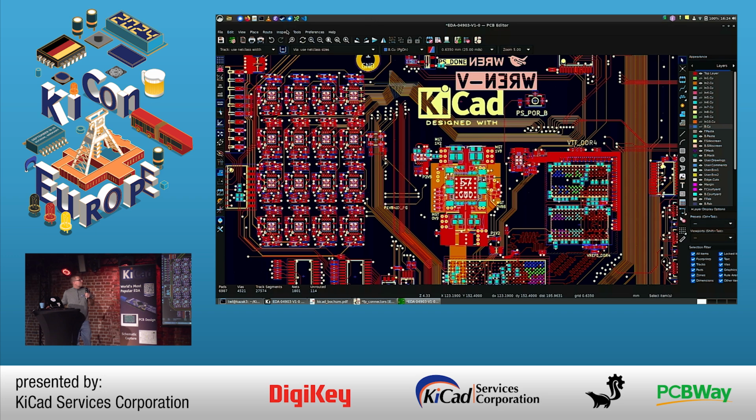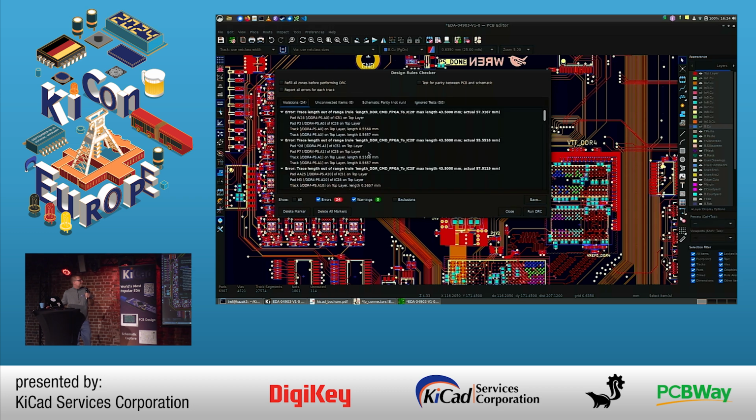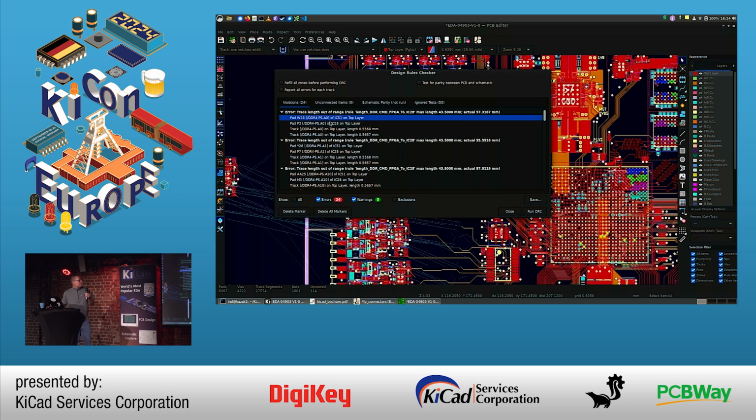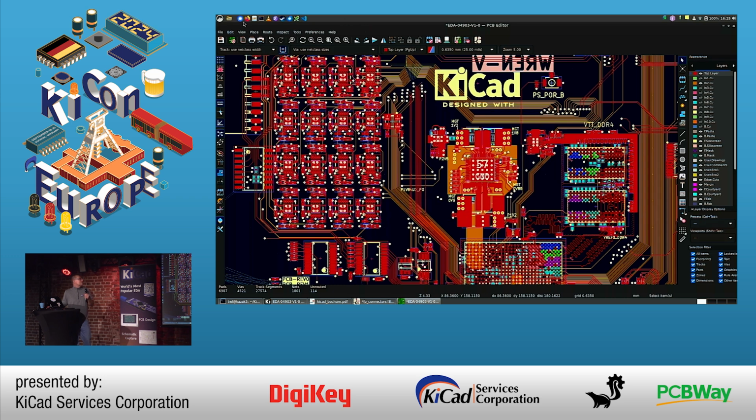Let's see what the DRC will tell us. Nope, we are out of range. But the rule only took into account the respective chips and signals, so only the control bus of the DDR. In this way, you can carefully constrain particular signals and signal groups in order to meet your routing requirements. There are a few more on this board.